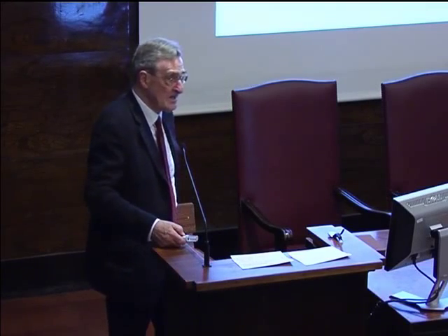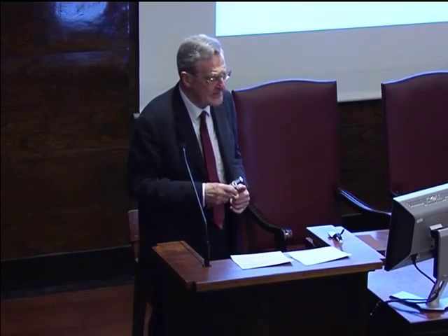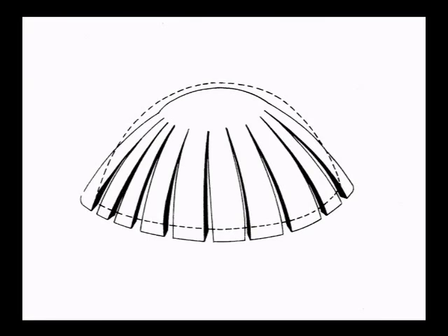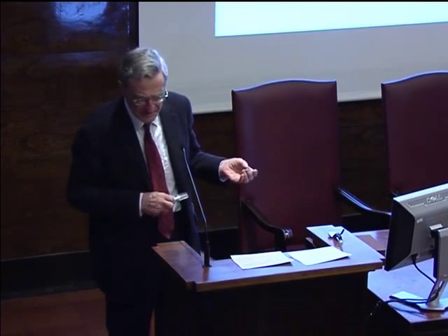So it is relatively easy, therefore, to find solutions for any practical dome. Now, just as our two-dimensional arch thrusting against the riverbanks exhibited cracking, so here, in a grossly exaggerated way, is what happens to a dome sitting upon a drum, and the drum perhaps expands in diameter a little bit so that the supports give way.